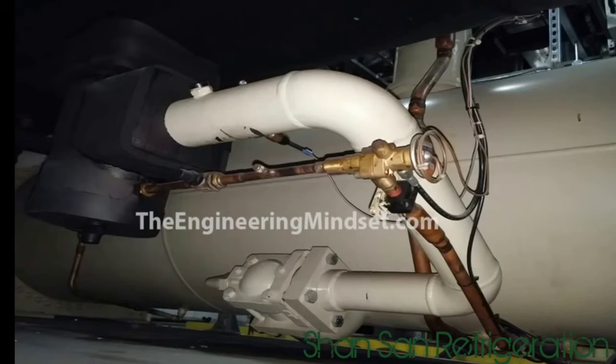To control this flow, we've got the pilot operated thermal expansion valve, and that is also fed refrigerant from the base of the condenser. This flows through this tube here into the valve. The valve decides if it can flow in or not. That flows through into the base of the main expansion valve, and this flow is what controls the main valve. Attached to the pilot expansion valve is this capillary tube. This rides up and attaches to a thermal bulb which is placed on the suction line of the compressor.